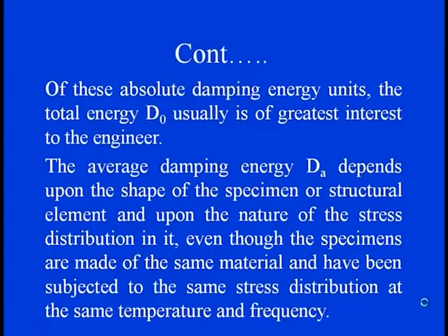So, when we go for our design part, and if we are trying to focus on the average damping energy dA, then we need to check not only the shape, but also the nature of the stress which is being distributed all across the material. We also need to check, when the material is subjected to the same stress distribution at the same temperature and frequency, what exactly the effect of these heat generations is.